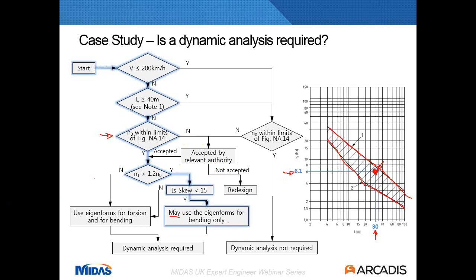Next question is, in MIDAS, when entering material properties, you can apply damping ratios to the materials. You can also apply modal damping when considering time history loads. How are each of these applied, and should both be considered, or is one preferred?